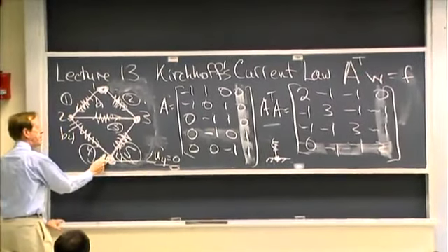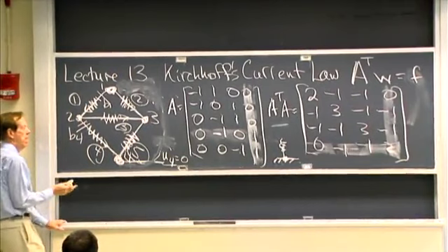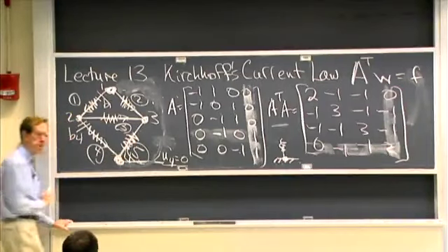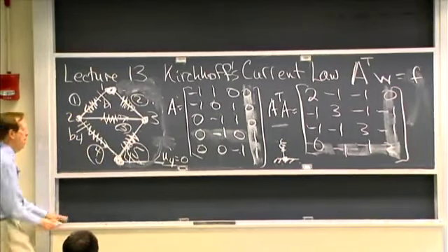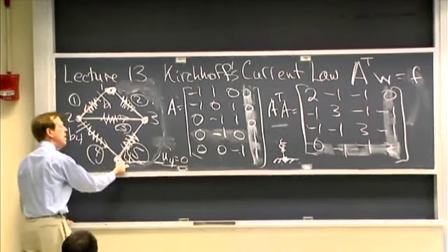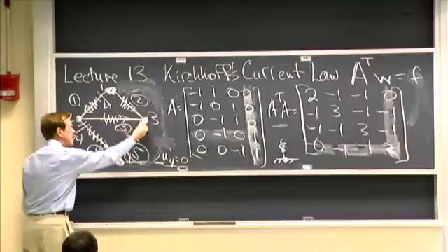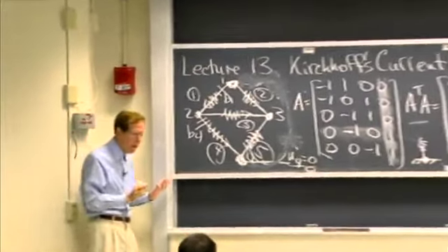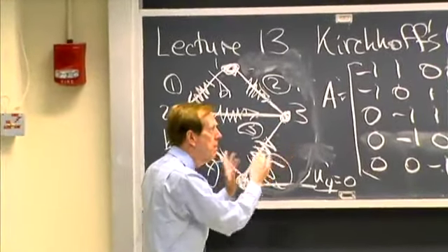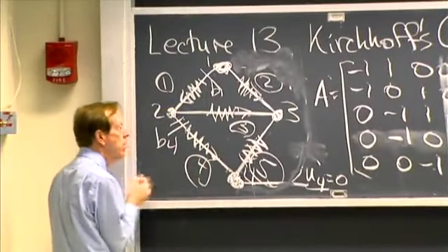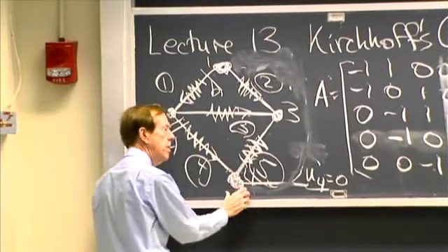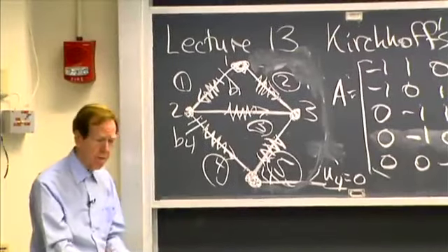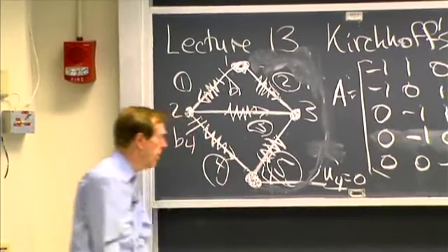At this node, what's happening? What's happening to the balance of currents? Does this current have to balance that current at the ground? No. Whatever current comes here plus whatever current here comes here goes into ground. Do you see the point? Kirchhoff's current law, the balance of currents, in equals out, is true, but it's not an equation I have to solve in finding the currents. It's something I can discover at the end. I can say, okay, how much current flowed from ground?